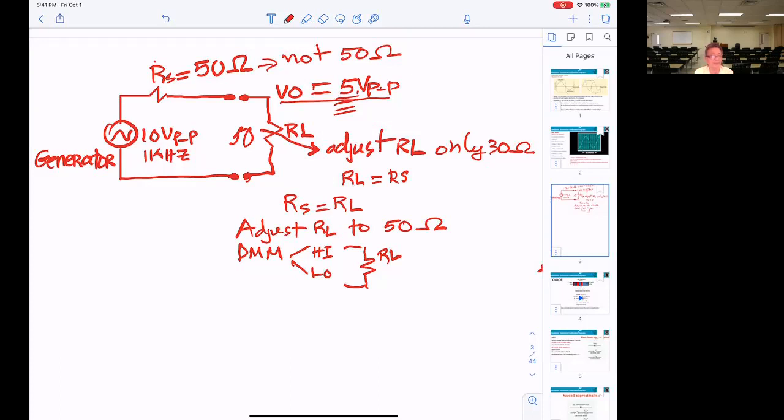Okay? So on the first part of the AC1, when you have to measure the resistance this way, I can tell you the value to get it part will be 50 ohm. Not a big deal. Otherwise, you have to get another circuit board. Also, Mr. Pham, you're saying on some of the lab boards, AC1s, this particular circuit block on some of them may not be working correctly.